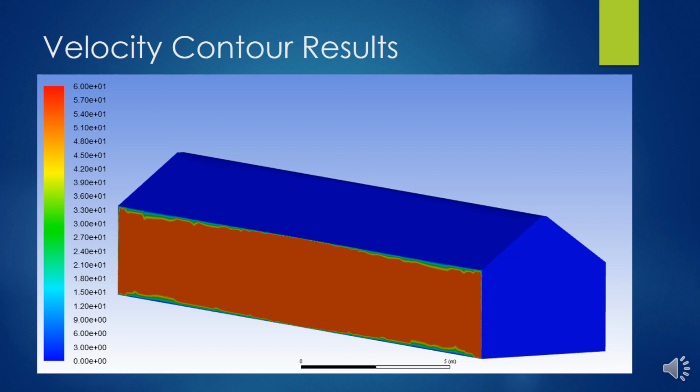Then for my run calculations, I put 0.01 for step time, and I ran 250 steps with the 50-step max. And voila, after that, I ran the velocity contour for the first 120 mile an hour wind, and that is this image in front of you.